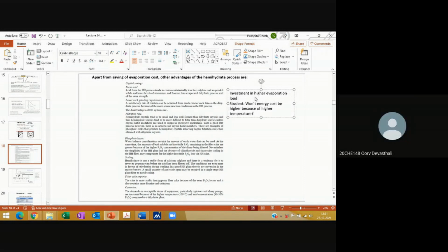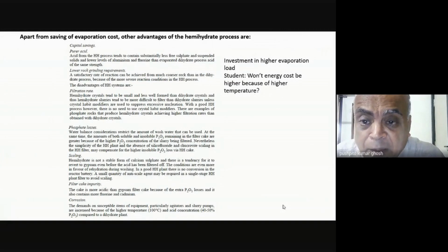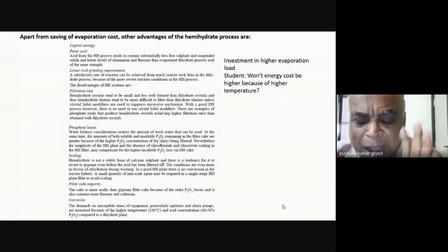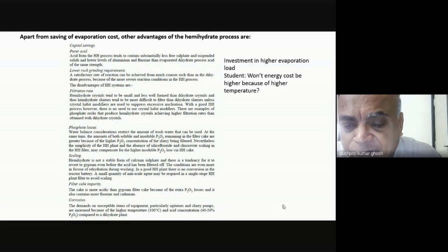Yes, yes. Okay. See, now what you have to do is take a much more holistic view. At the end, I'm trying to make phosphoric acid with a certain concentration. If I make it at the lower temperatures, that's fine, but one is that my rate of reaction is lower. So temperature per se alone cannot dictate it. I will have to see over how much time I'm applying the heat. So I have to integrate that and see the total amount of energy that I consume.